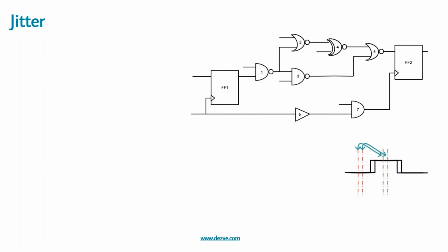Now, do we actually need to add the jitter? For setup, jitter would also be specified in some ppm or some percentage of the clock period, correct, some 10% or whatever. So for setup, the thing was like this: we have the maximum delay and the minimum delay here, and we said that we'll deduct the jitter value from the clock so that the clock becomes slightly earlier, and then we'll try to make sure that this maintains the setup requirement.